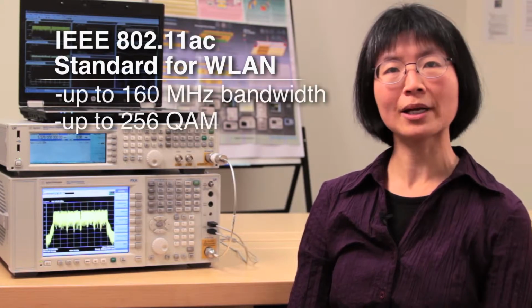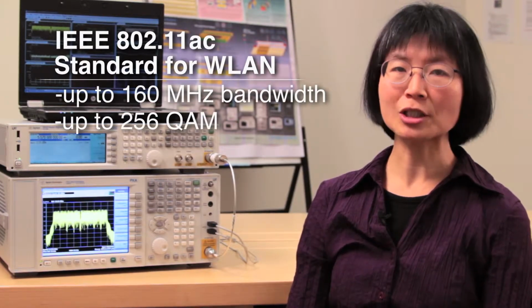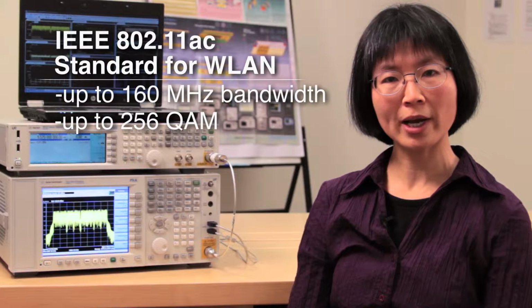The IEEE is developing a new standard for wireless LAN called 802.11ac that uses up to 80 or 160 megahertz of bandwidth and higher order modulation up to 256 QAM. This new standard enables end users to achieve higher data rates to support services like high-definition video and simultaneous data streaming. Because of the wider bandwidth and higher order modulation schemes, engineers face new challenges in designing their 802.11ac components and devices and testing the RF performance.